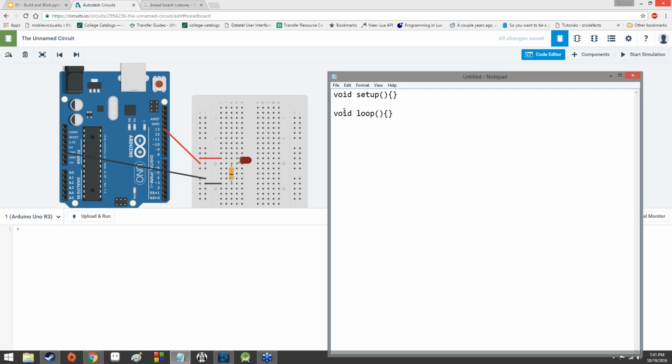These are functions. These are blocks of code that can be repeated. Because the way an Arduino runs is you turn it on, right? And it starts to basically load the program that you've written into the registers in the CPU. Fancy terms, don't worry about it for now. Void setup is always going to be the first thing that runs whenever an Arduino first gains power and first starts running its program. It's always going to be void setup. And void setup is always going to run once. Setup is where you set up everything that you need for your program to work predictably. It's kind of why it's called setup.